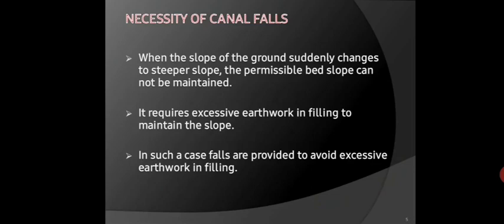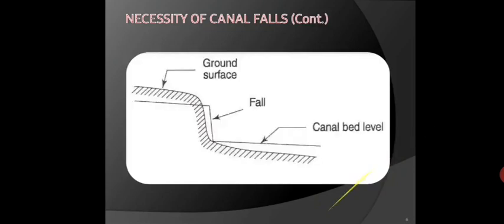Here is the point: when the slope of the ground suddenly changes to a steeper slope, the permissible bed slope cannot be maintained. It requires excessive earthwork in filling to maintain the slope. In such a case, falls are provided to avoid excessive earthwork in filling.